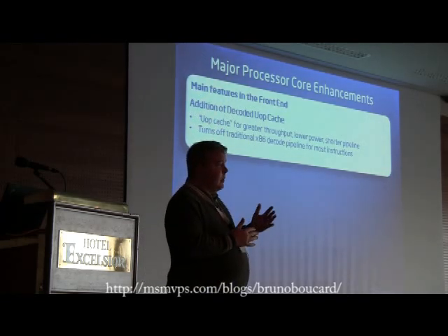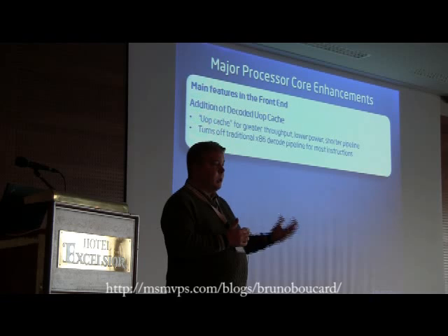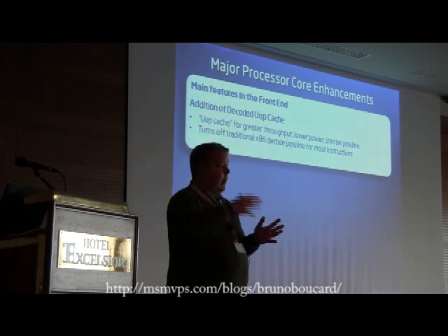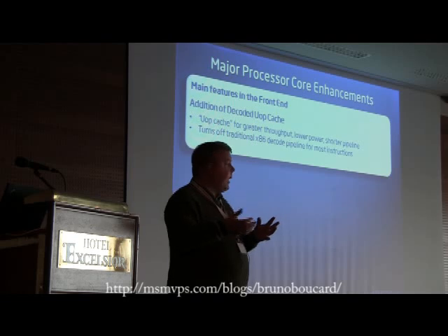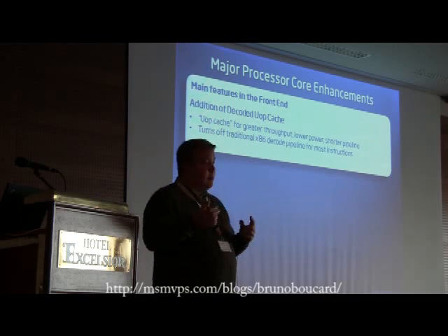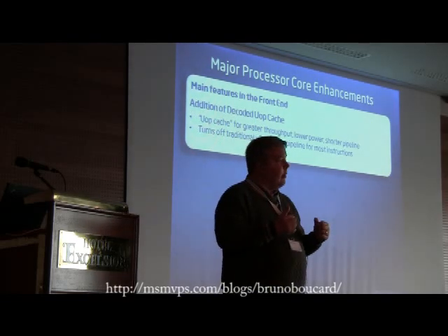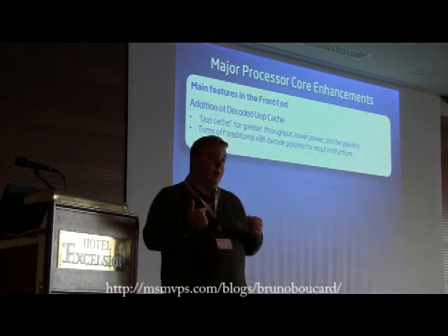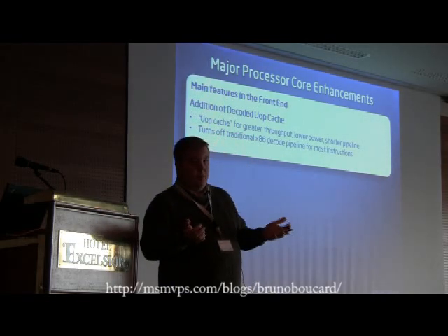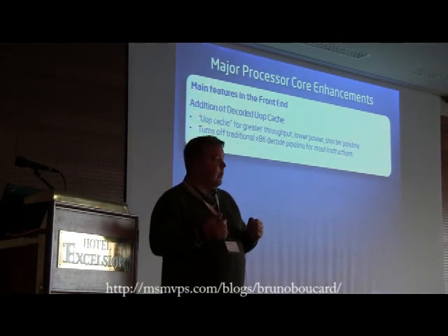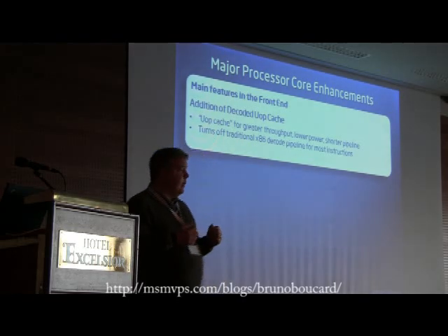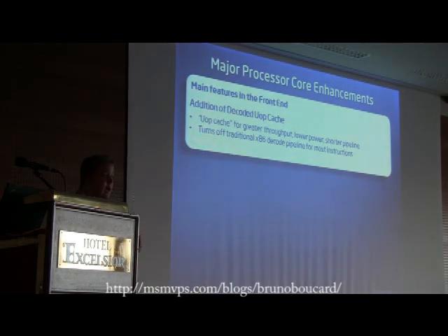And now what we've done is we have both powerful decoders and instruction cache up front. We now have added a slightly different version of the micro-op cache back in. That allows us to run with the decoders turned off frequently. Why does that matter? Decoders chew up a lot of power. So the power savings that we can get in the core is due also to this ability to have the cache and the micro-ops.